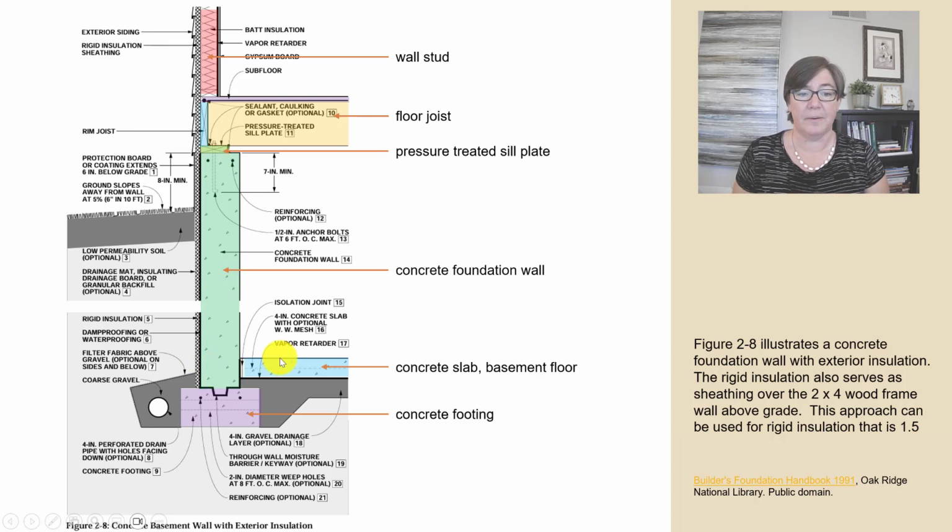And as we go down to the basement floor here, that is a concrete slab. And at the bottom of all of this is our concrete footing. Right? Notice that it's wider than your foundation wall because it's bearing directly on the soil below. We want a nice wide pad for that.